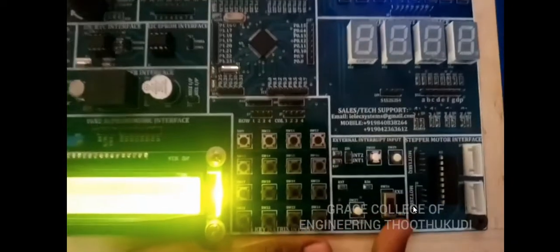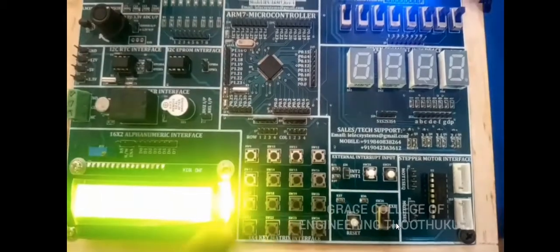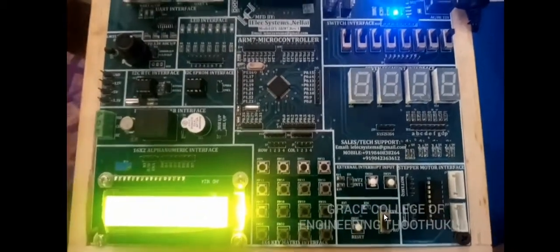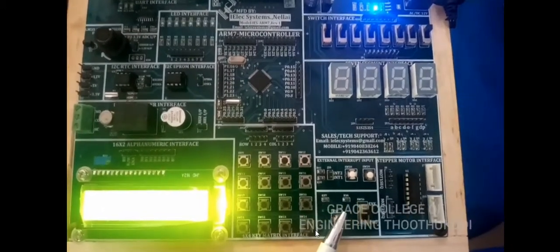While downloading the program from our system, we will be keeping the switch in program mode. When we want to view the output after dumping the program into the kit, maybe it may be an LED output, or we need to display something on the LCD over here, or we need to hear the buzzer sound, whatever output we need to check using this ARM controller, you can push this button to execution mode and press this reset button over here.